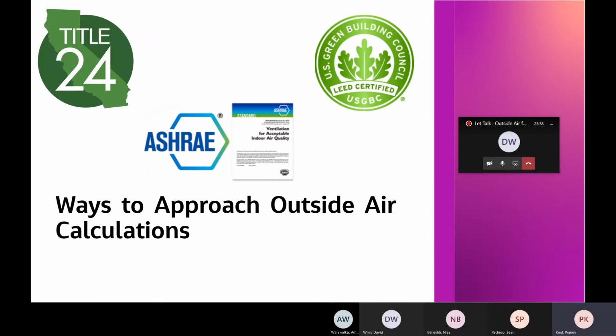All right. So the ways to approach outside air calculations. Over here, I will be talking about Title 24, ASHRAE, and LEED version 4.1 requirements and how they are in sync with each other, and some of the differences. I'm going to do a little bit of a comparative study of their requirements, knowing that both of them are based on ASHRAE 62.1.